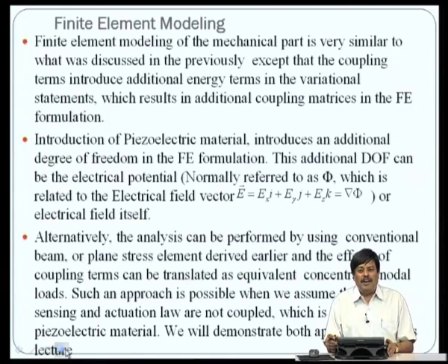So, now coming back to the finite element modeling. The finite element modeling of the mechanical part, which is epsilon equal to S times sigma, is very similar to what we discussed in the previous lecture, except that the coupling terms introduce additional energy terms in the weak form of the governing equation, which would result in the coupling matrices in the FE formulation.